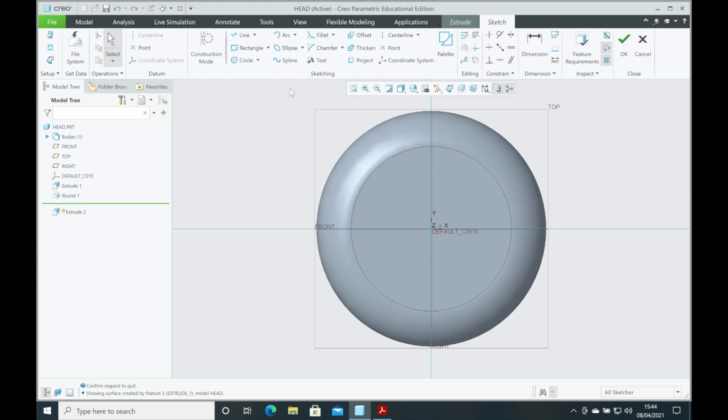So it's exactly the same process as before. We click on the circle, we're going to draw from the center out, and then we go back and resize it. Now please remember to draw just one circle. We don't want more than one circle. So we click once, which will end about there. We go to that select button again, really important, we don't press anything else. When we press the select button, the circle will change colour, so we know we're good to go, and we'll get that dimension come up.